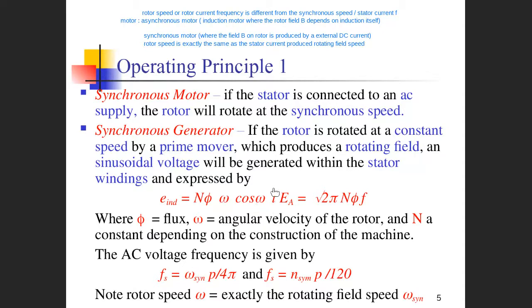Meanwhile, the electricity has a cosine or sine waveform, with a frequency omega that depends on the rotating speed as well as the number of poles of the field coils. And this is the instantaneous generated voltage changing with time, with angular frequency omega.